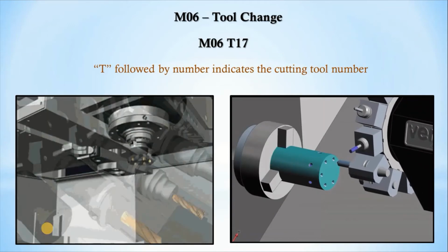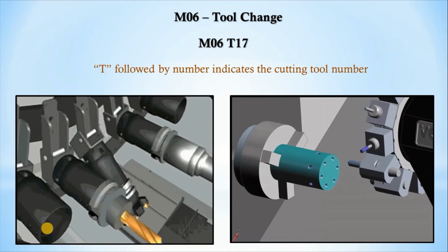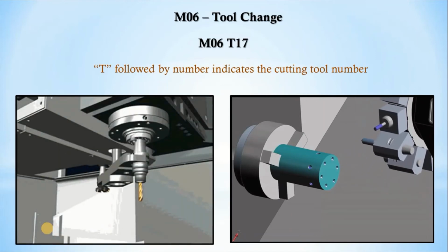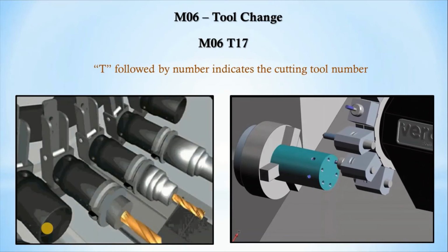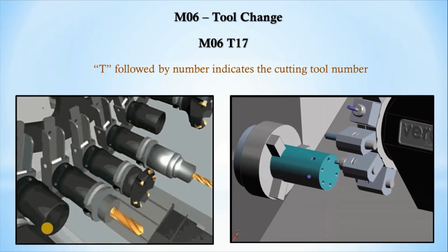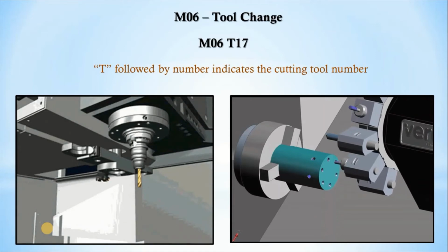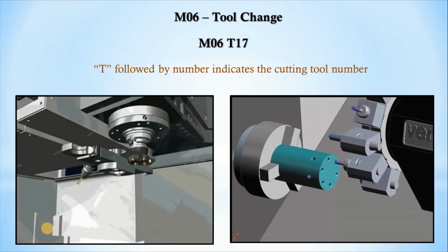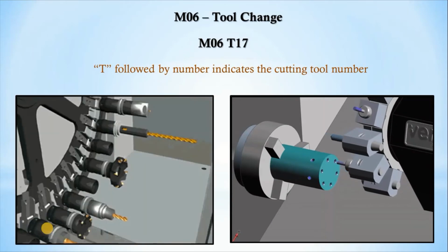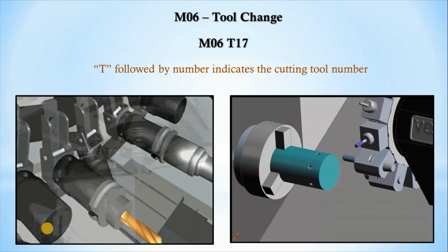for changing the tool. As we have seen, the block numbers which are given are in incremental numbers, because that gives a facility for modification of the program corresponding to a design modification. If we write the block numbers in the program, that is a benefit.